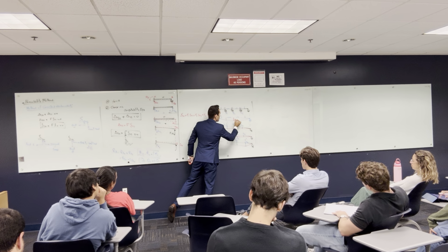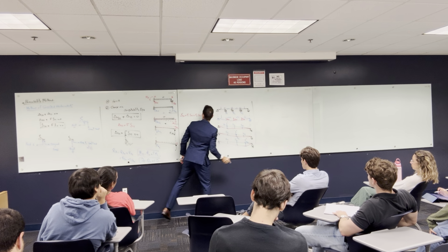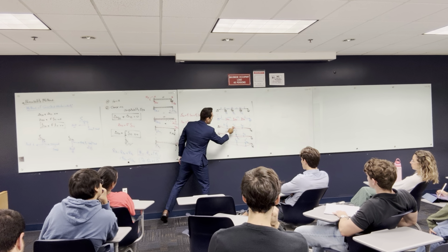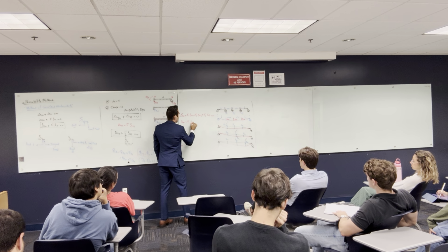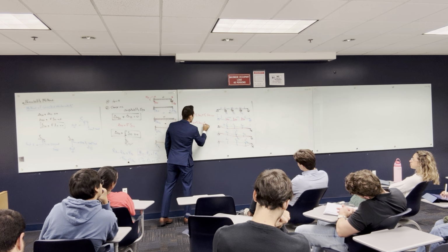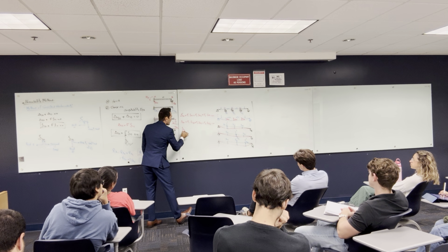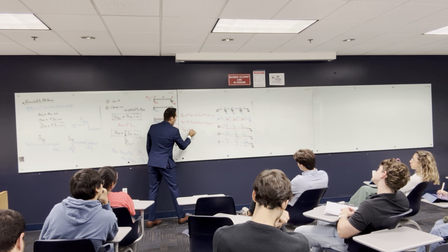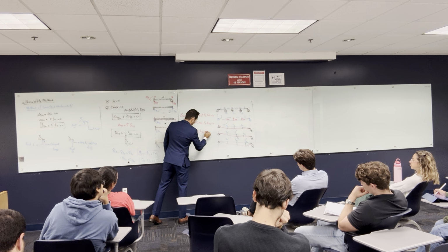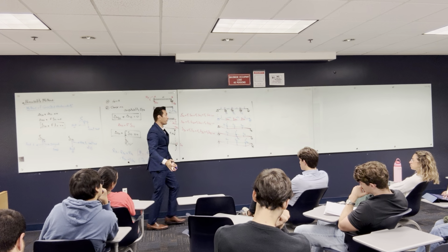Equation number 2 is delta 2O plus F1 delta 2,1 plus F2 delta 2,2 plus F3 delta 2,3 should be equal to 0. And the third one, delta 3O plus F1 delta 3,1 plus F2 delta 3,2 plus F3 delta 3,3 equal to 0. That is the 3 compatibility equations.